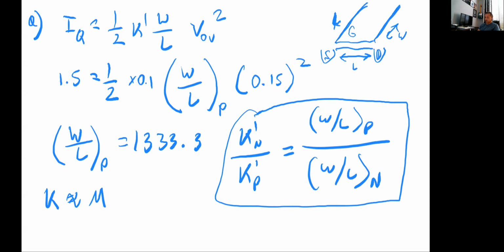We call this the length of the transistor because that's when you draw the polysilicon. When you draw a transistor, you draw it with that length of the polysilicon, and this becomes the width of the polysilicon because this is the critical dimension. So when you hear about a 3 nanometer technology node or something like that, they're basically saying that this is 3 nanometers, and that's the width of the polysilicon as the transistor gets constructed. So that's something to keep in mind as we go into the next chapter, which is about the integrated circuit design of analog